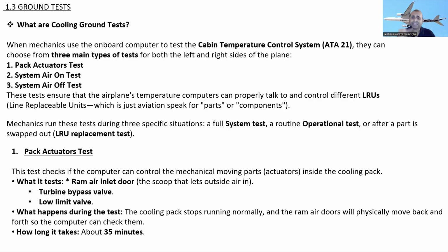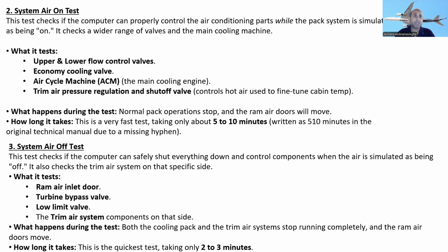What happens during the test? The cooling pack stops running normally, and the RAM air doors physically move back and forth so the computer can check them. How long does it take? It takes about 35 minutes. Now let's go to the system air on test.